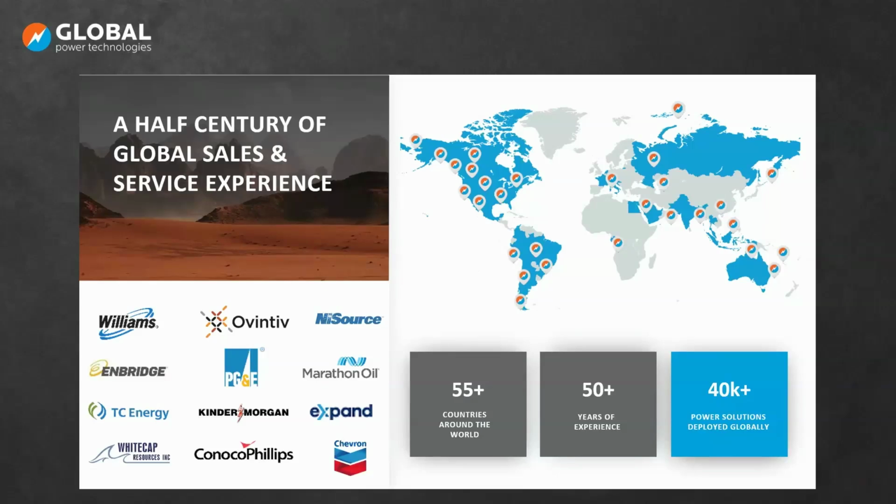Let's see, Adam, maybe I'll pass this next one to you about whether raw gas at a wellhead can be used, or what we would look at in the fuel composition to determine whether either gas pressure reduction or fuel conditioning might be required. Yeah, so a lot of our installer locations actually do use raw gas. Like you said, it does depend on the fuel composition itself. So we've seen areas that either have high CO2 concentration or H2S concentration. So in those areas, we do have fuel conditioning systems that we use. Typically, those are installed on like an offshore platform.